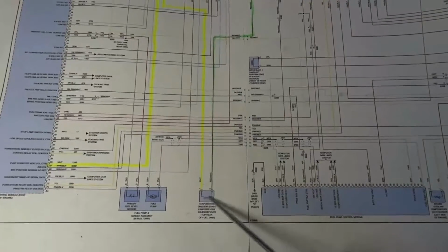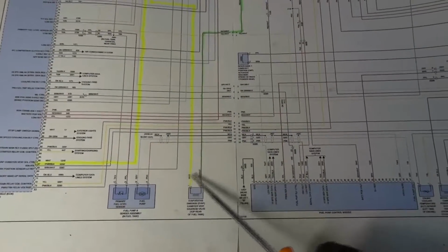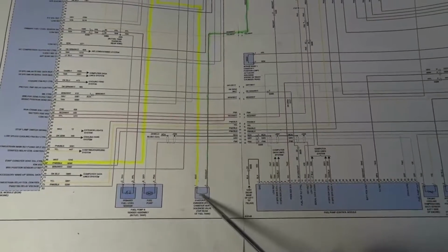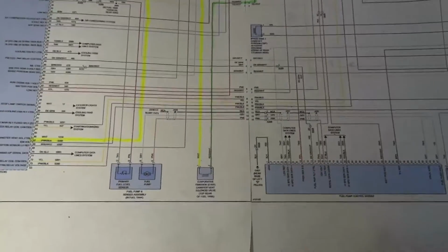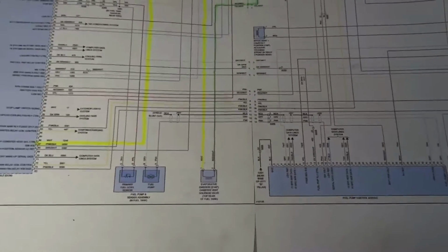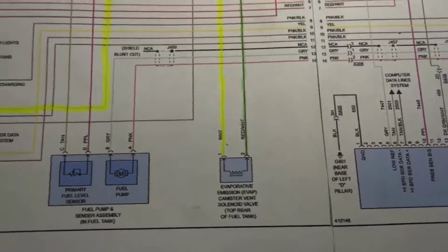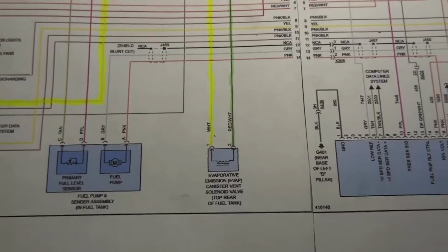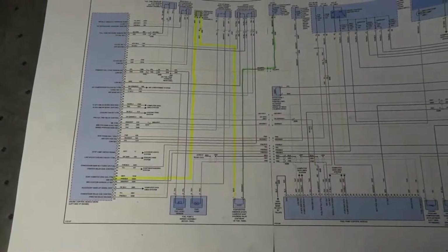The problem is an open vent solenoid, because since our test light lights every time we command the vent solenoid on, that means the wiring is good. The problem is the open in the vent solenoid itself, okay? So this vent solenoid over here has an open coil, so the winding in the vent solenoid is open. All right, so I feel confident replacing this vent solenoid.